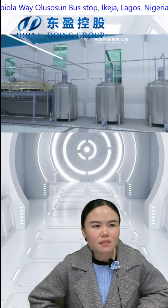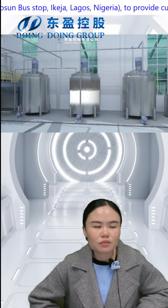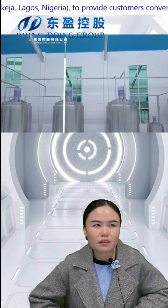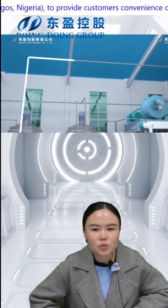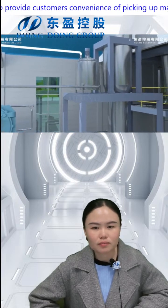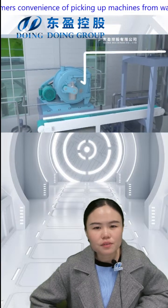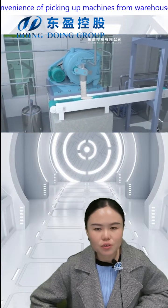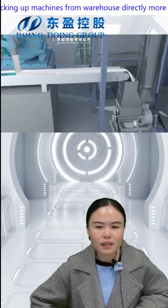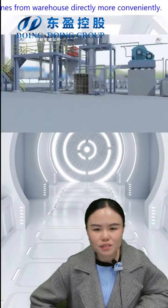After that, the purified starch slurry will be stored in our buffer tank, and from the buffer tank, it will be pumped into the dehydration machine, the pillar centrifuge. This pillar centrifuge will dehydrate the starch slurry, and after the dewatering process, we can get wet starch powder with around 38% moisture.